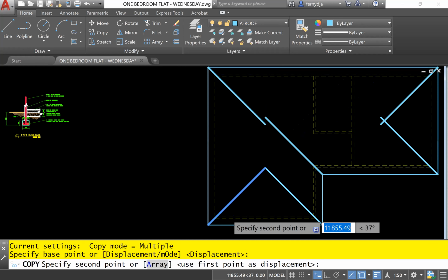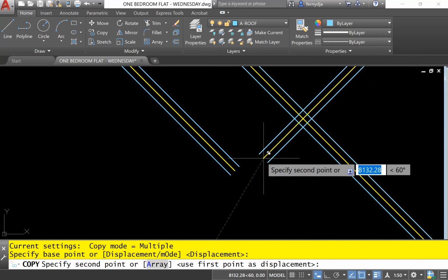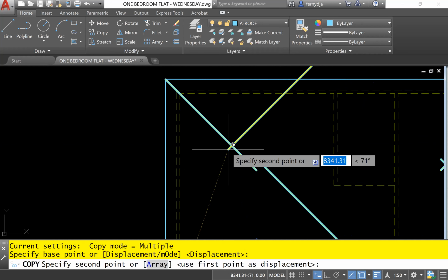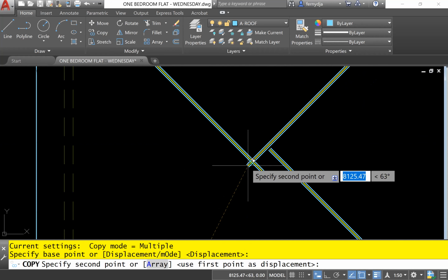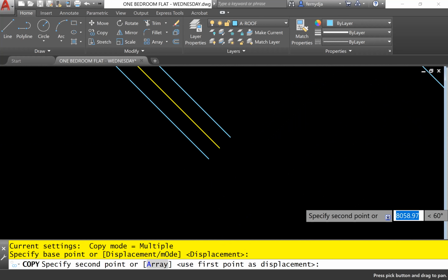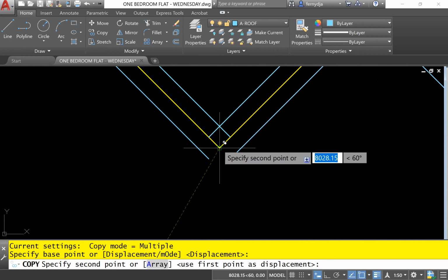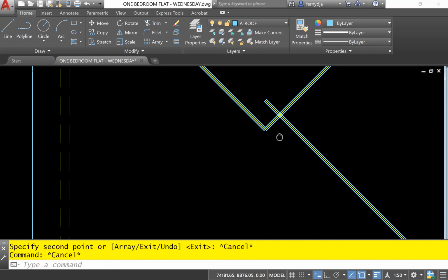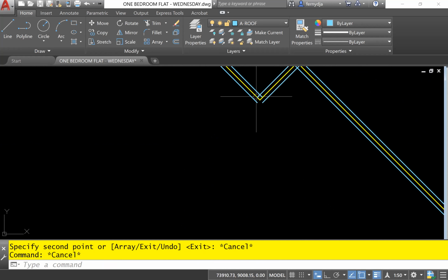And look at where I'm going to put it this time. I'm going to look for these 3 lines. So I'm talking about these 3 lines here, coming down, and at the end of this middle line, which is why I told you to change the color so we can find them easily. So I'm going to coincide the endpoint of that line with the endpoint of this line. Good. So that now will give you where the apex is.